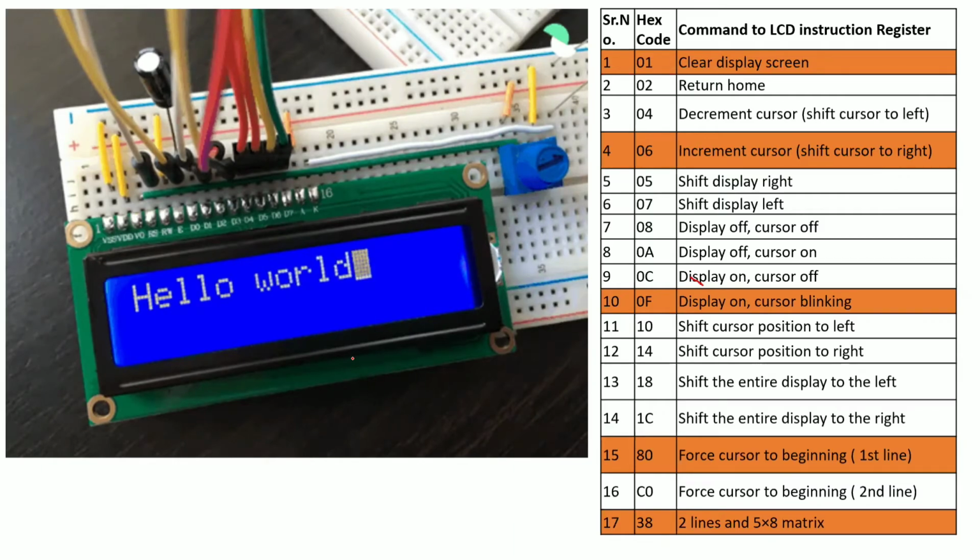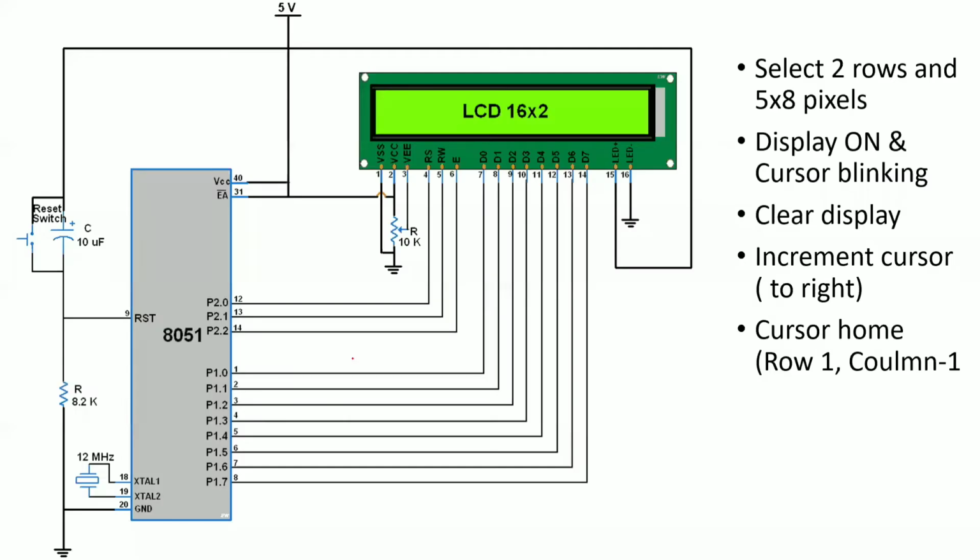And we are going to see how to interface this 16 by 2 LCD display to your 8051 microcontroller. Now you can see your 8051 microcontroller has ports. I'm sure whenever you want to connect any input or output device to your microcontroller, you need to use ports, right?